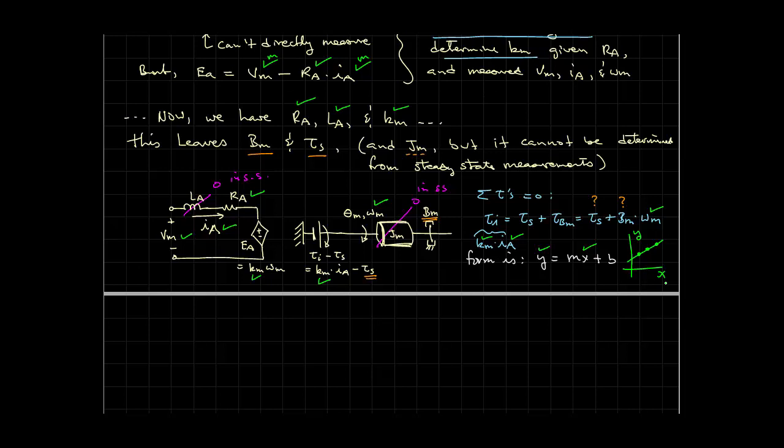For instance, if you apply a voltage to the motor and you vary the voltage on the motor, say from 0.5 volts up to 3.5 volts, you can imagine that the speed of the motor is going to change significantly over that time. But do you know how much the current will change over that span of voltages? If the motor is unloaded, the current may not actually change significantly.